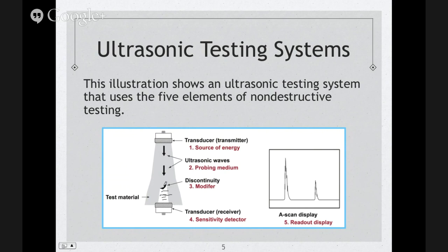Now, if we didn't have this discontinuity, maybe this would be a higher amplitude. But because we're losing sound here, all this sound is reflecting back. We're losing all this sound, so we're just getting the sides. Now our indication is going to come all the way, and it's going to lose amplitude as it did in this example.